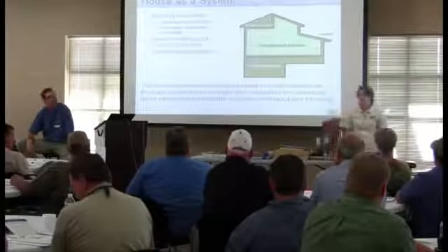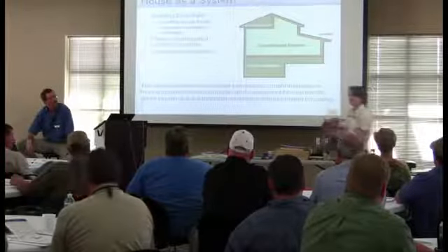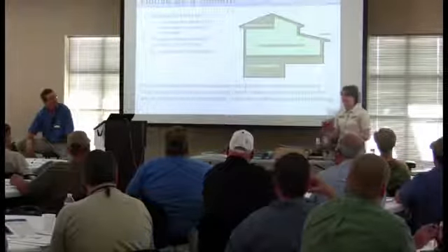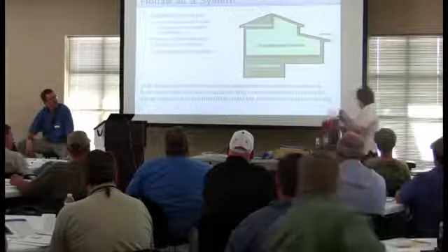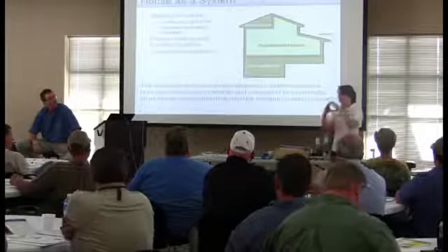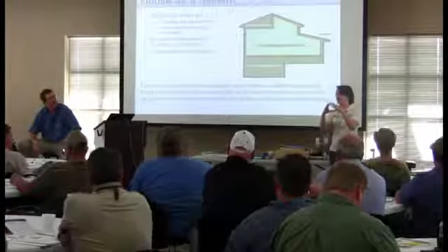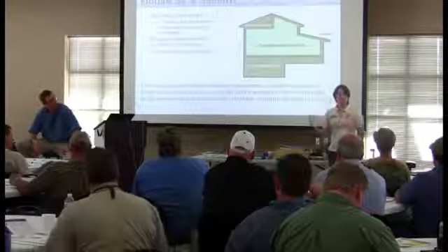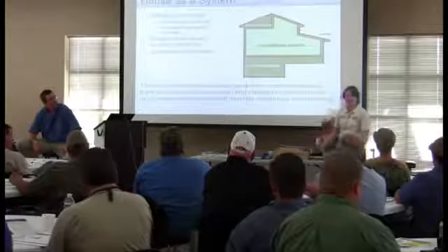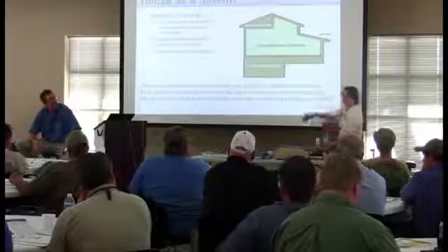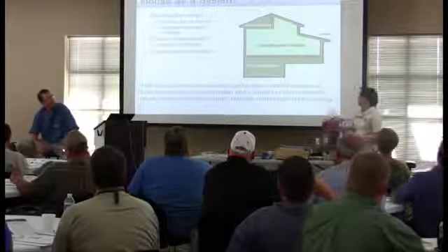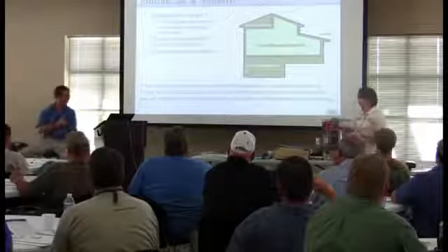So what we're asking is that we reduce the size of the actual hole in the house, through infiltration, through air leakage, and that we cut a small hole about this big and ventilate. I would trade a hole this big for one this big where I actually know where the air is coming from. Because when you cut a hole in the house and ventilate from it, you know where the air is coming from. It's probably not coming from the crawl space or the attic like our traditional hole, because we don't know where those holes are. Those are just missed seams. So really keep ventilation in mind, bringing in fresh air for our occupants.